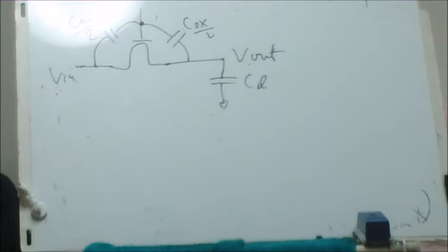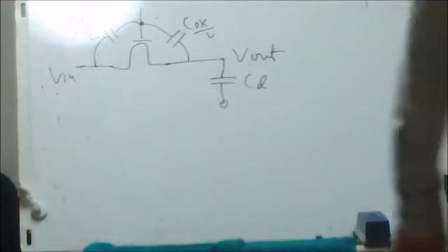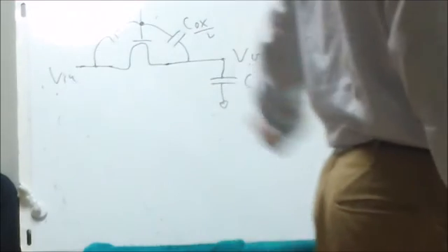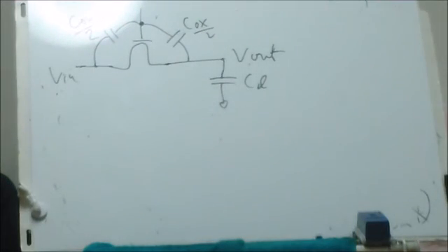However, as the switch turns on, the input signal is connected to the load capacitor through the NMOS switch. The result is that C load is charged to Vin and the clock feedthrough has no effect on the final value of Vout. However, now consider what happens when the clock signal makes the transition low. When it turns on, there is feedthrough, but it goes to this side so ultimately there's no effect. Then what happens when it switches off? When charging, the final value is determined by Vin, but what happens when it's cut off? That is, the N-channel MOSFET turns off.